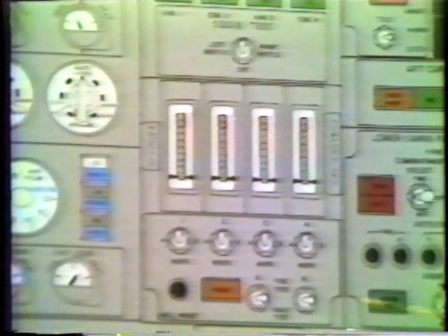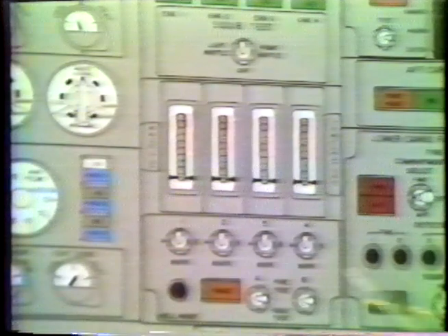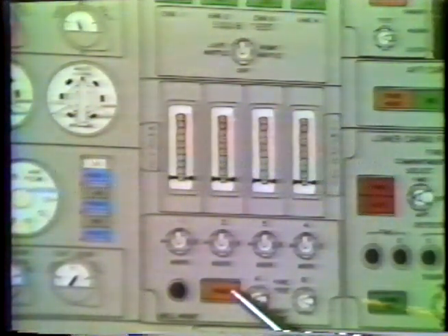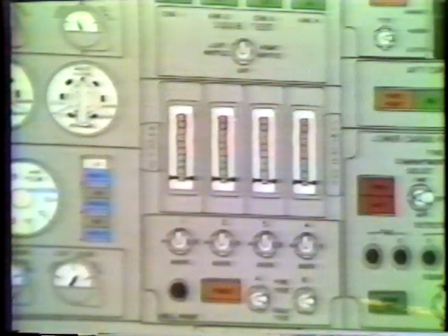On the 747, if you get a fire warning, you better believe it's a fire, because it's a very, very reliable system. A fault light coming on will also illuminate a fault light in the master annunciator panel on the center instrument panel. One can't come on without the other.